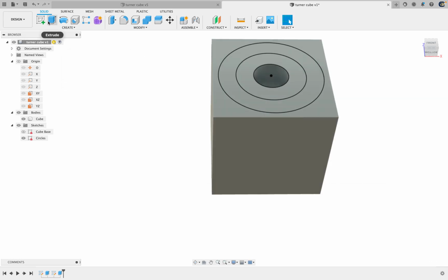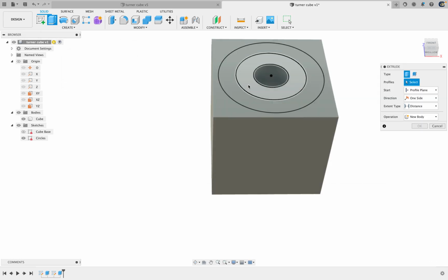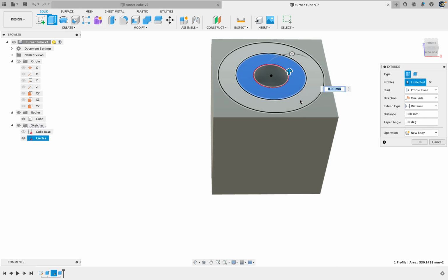Because on this new extrude, I'm going to do it for real this time. I click that second circle, and the distance is going to be negative to make it cut. And then I'm going to do parentheses. We'll type in big cut or whatever you named yours. Oh, and I don't even need those parentheses, sorry.